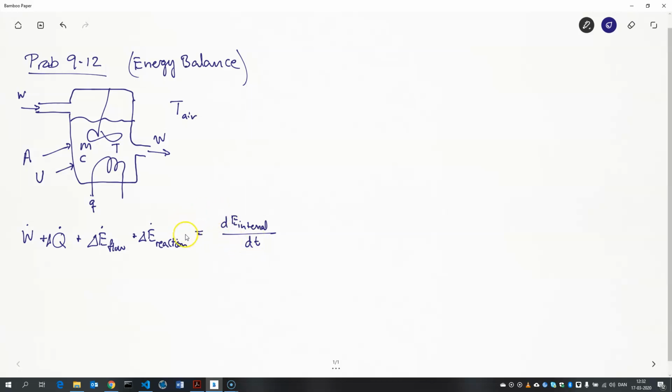So that's the general energy balance. And it's a no-brainer to cross out this term here because there's no reaction going on in our tank. And also we will neglect the work done on the system by the surroundings. We're talking about the agitator here. It does put some energy into the tank by this rotating movement, but it's minute compared to the energies involved with the temperature changes and the heat supplied by the heater.